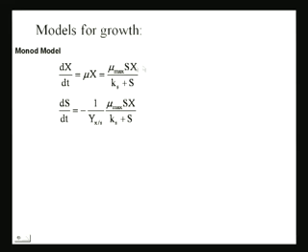So here we have used this as my yield, reaction rate for x. So you have to convert that into S. If you're doing a molar balance for S, then if the yield of x per unit of S is Y, then 1 over Y is the yield of S per unit x, right? So you just multiply by that number. So this is my basic equation for a batch reactor, and what we do now is try to express x in terms of S.